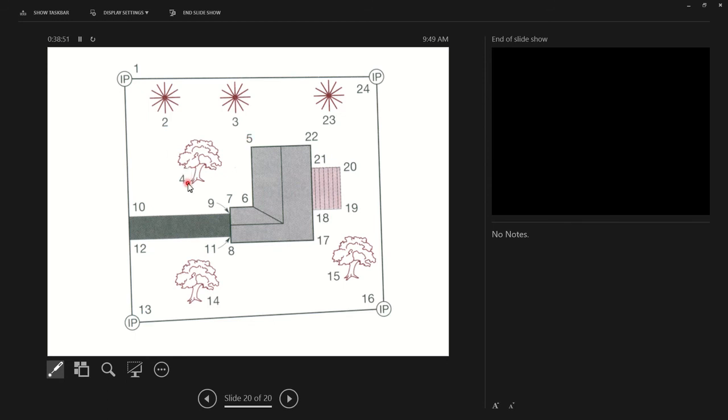And then we jump down to a deciduous tree at number 4, which is a DTRE. Number 5 would be your building, so it'd be a BLDG space B because you're beginning the building there. 6 would be BLDG, 7 BLDG, 8 BLDG, okay? But when we jump up to 9, 9 would be a sidewalk, so we would start a sidewalk code there, so it'd be SW space B, sorry. ST was the old codes I used to use at my tech. So this would be a SW space B. We go over to 10, be SW. 11 now, we don't want to call it SW. We're going to have to start 11 again with an SW space B.